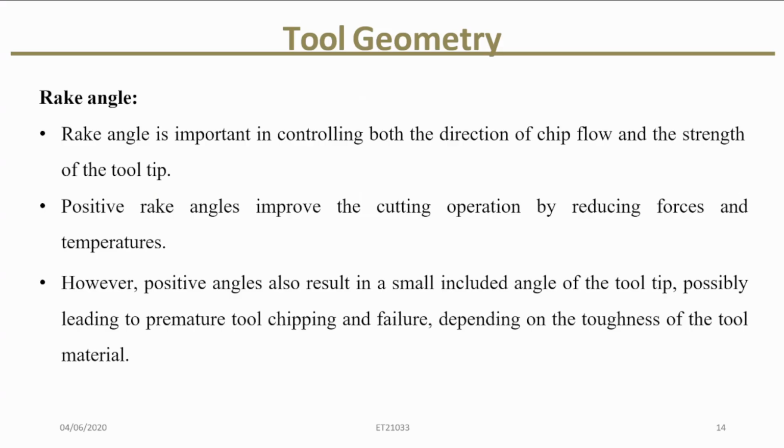However, positive angles also result in a small included angle of the tool tip, possibly leading to premature tool chipping and failure, depending on the toughness of the tool material.